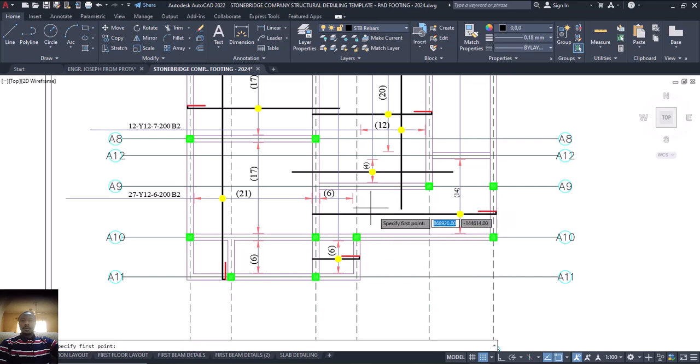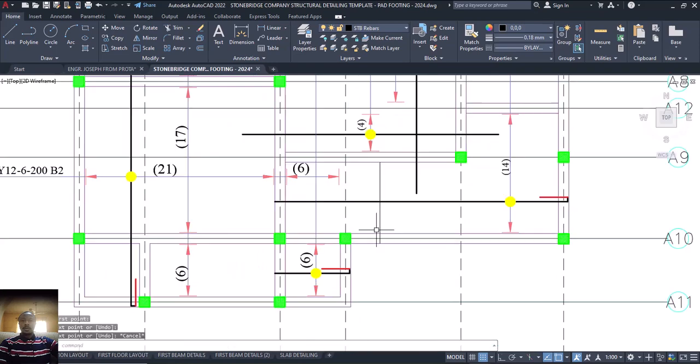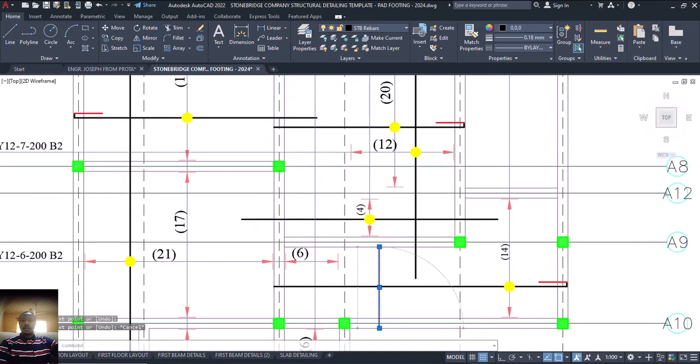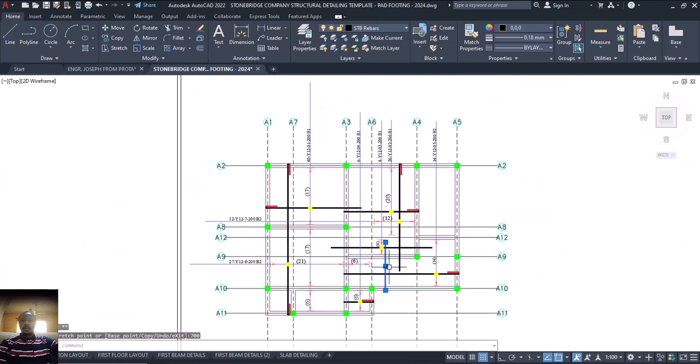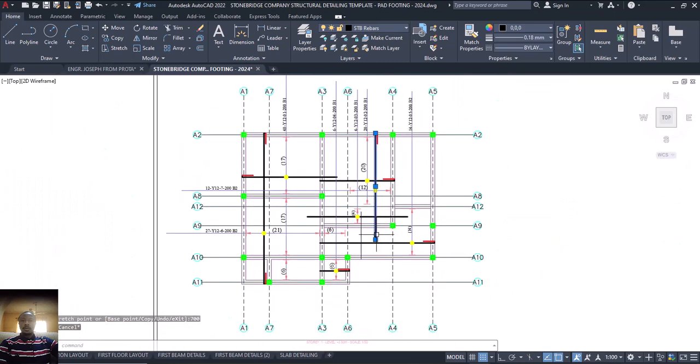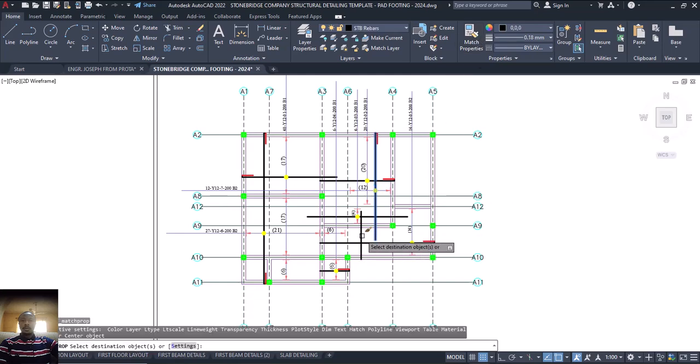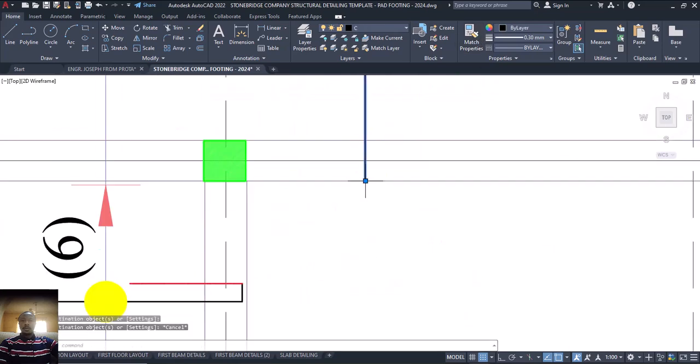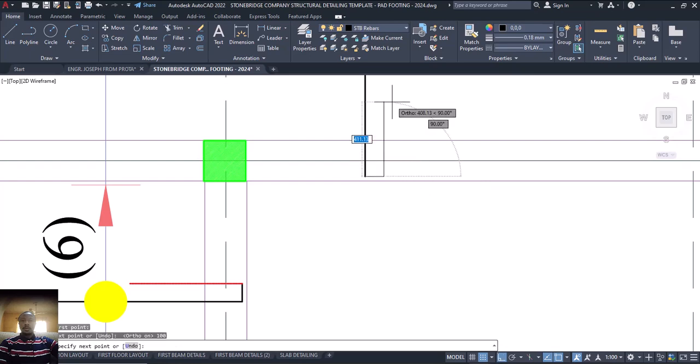L, enter. This place now becomes my this. Okay, take this one to this place. Okay, for lapping, let it enter inside by 700. Okay, proper lapping is okay. Collect this one, match the property. This one, perfect. Then this one, my concrete cover 25. Okay, then L, enter. Is that okay? Then 100. Then return bar 200, 600. Then enter. So that is that.